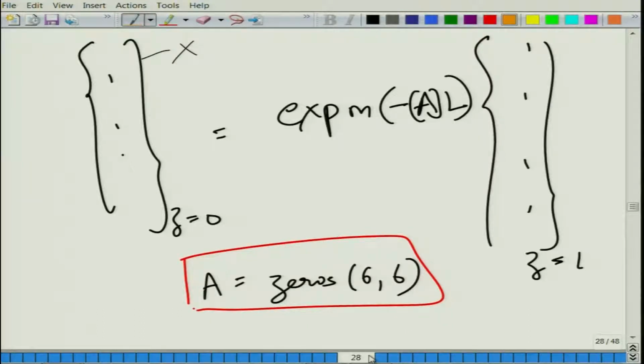So, again this is the command. Now, just one small digression that I would like to make. Prior to this work, ages back, when the analysis of perforates first started, the work by Sullivan and Crocker, they used a segmentation approach. They used to divide the duct into a number of small parts and get transfer matrices across each part.